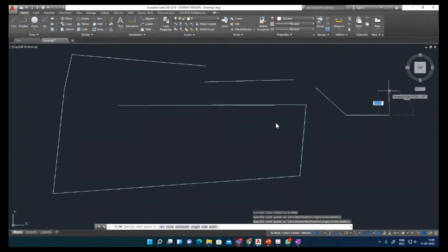Then you have separate segmentations. Each segmentation you can take into AutoCAD, and then manually, using this polyline, you draw the boundary this way, and then you can create a region, convert it into surfaces, and after that you join all the surfaces and you will get an irregular solid model of a bone or whatever you have selected for your study.